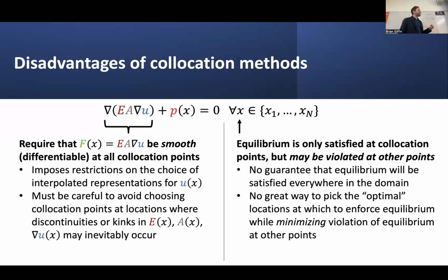This is really one of the problems when you have these governing differential equations expressed like this. It basically means that if I have any kind of discontinuity, it could also be a discontinuity in the member cross-section size. So two distinct members of differing cross-sections joining at one end could mean that if there's a discontinuity in that representation, then I can't take the derivative there. The derivative is not well defined at that location.